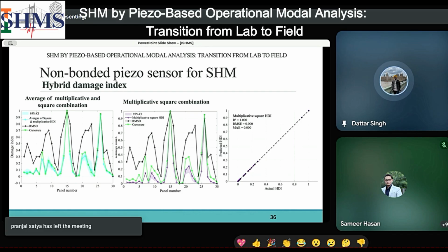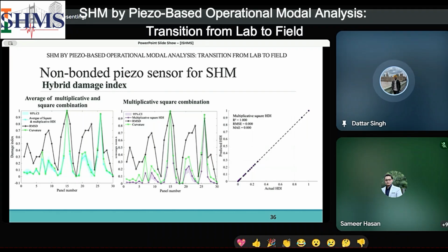So now this combined damage index, based on local monitoring and global monitoring, gives us a new effective damage index for robust damage monitoring and damage detection, with the measurement noise being least or insignificant at non-damage elements.